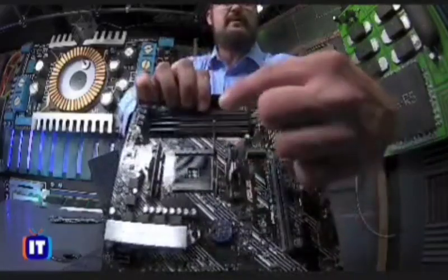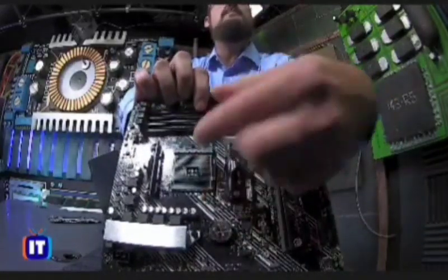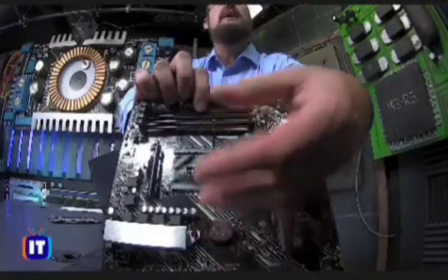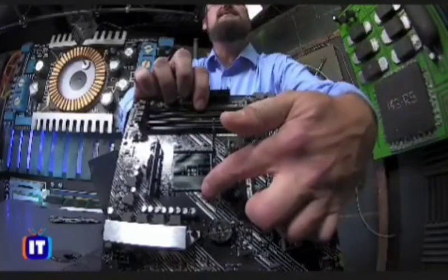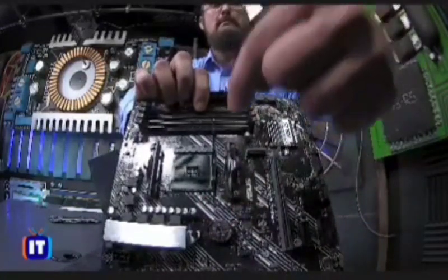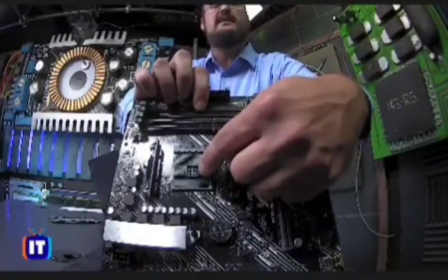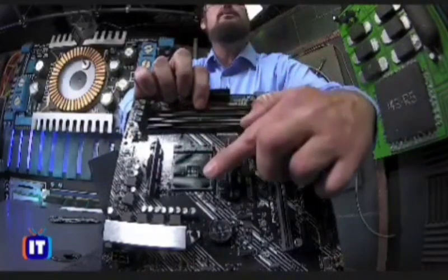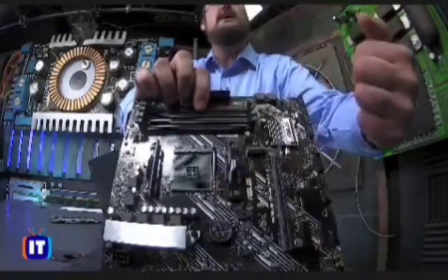So they came up with a socket that, when you open it up, you can see it moves a little bit. It opens the ports in the base of the socket all the way. You mount the PGA-based CPU, and then you push this arm down, and you can hear it click there. That locks the CPU in place so that it prevents chip creep. That was one of the most common implementations for a long time in AMD-based processors, but it's not the only one out there.